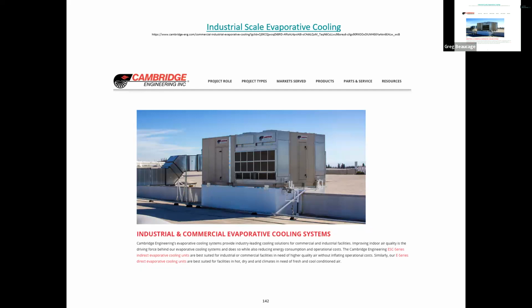So large scale frozen fish and frozen vegetable plants use gigantic ammonia-based evaporative coolers. Because when you evaporate ammonia, it takes a lot of enthalpy out. You can put it through a process. Ammonia will absorb into water or can absorb into other things. You can condense it. You can chemically condense it. And then you can use the heat to drive the evaporation. And the evaporation of ammonia is at -10 or -20 C. Right, so that you can get a significant cooling. If you change the pressure on the ammonia, you can get it even colder.